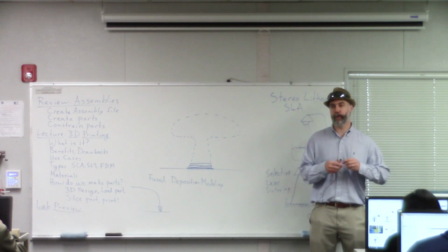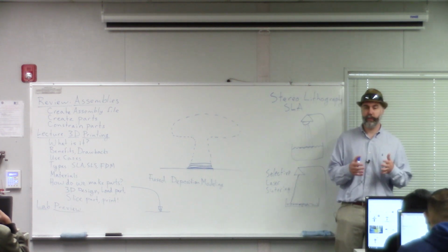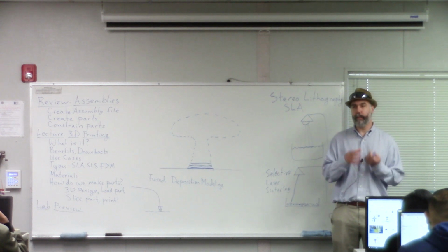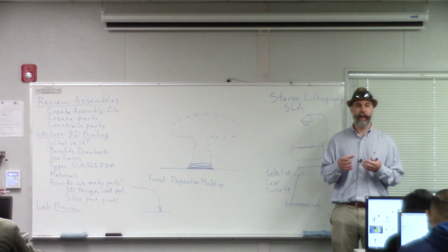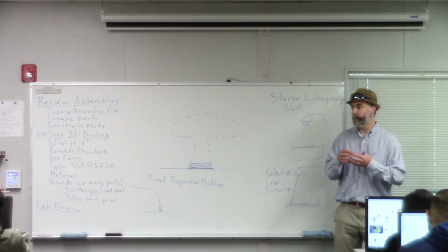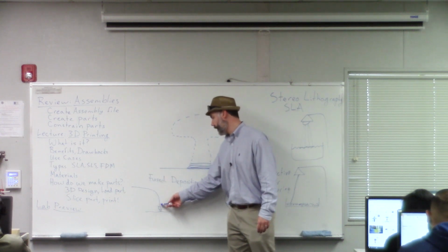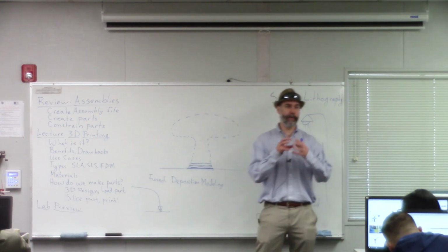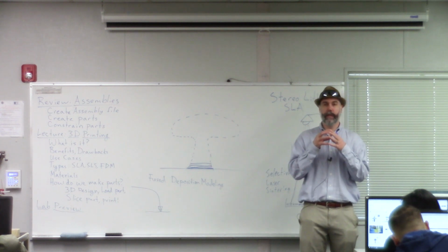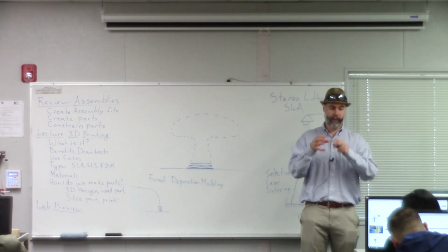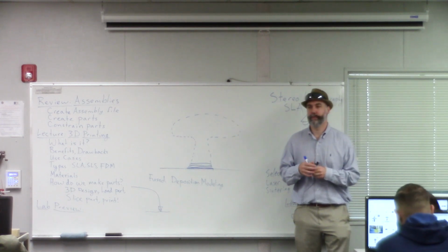And then afterwards, you can use a process called sintering, which is basically where you bake that part for a certain amount of time in an oven. And what that does is that melts those little tiny metal particles that are inside of that filament, and those particles melt together and they fuse with each other, and they become a semi-solid structure that way.